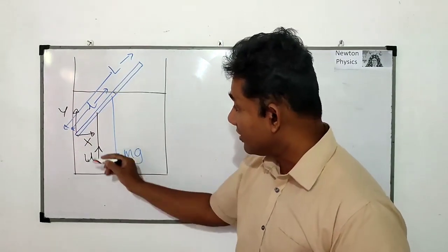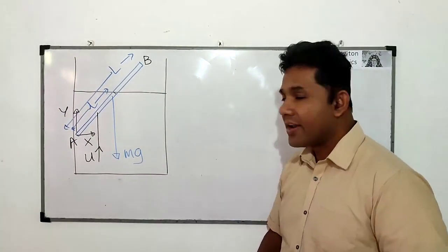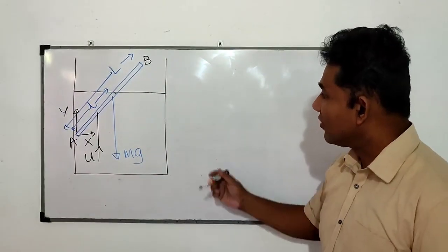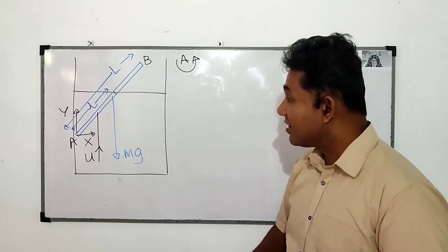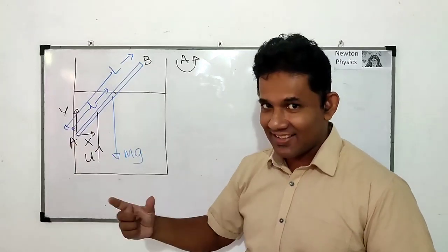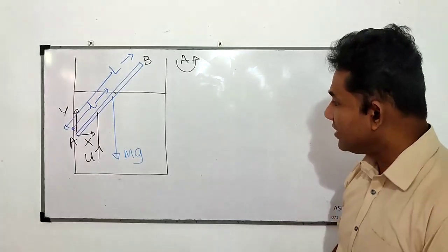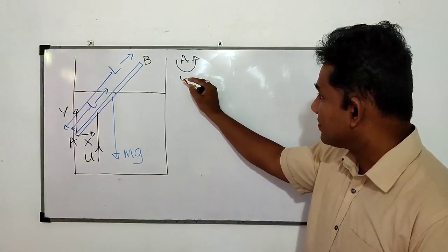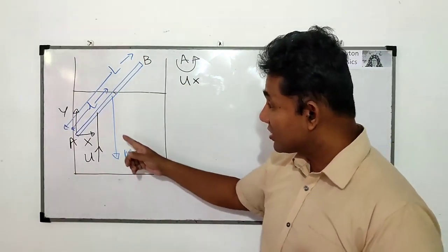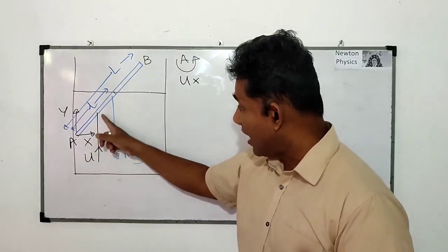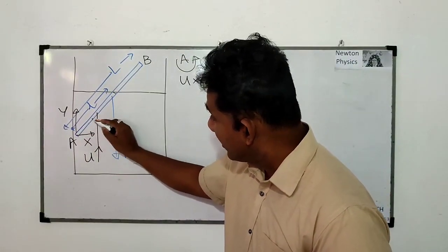That means, if I take the rod as AB, I consider moments around capital A, and that's why the x and y forces are cancelled. Now I am taking the moments counterclockwise, so think about the upthrust U. I need the perpendicular distance between point A and the line of the upthrust U. Here think about this small length.